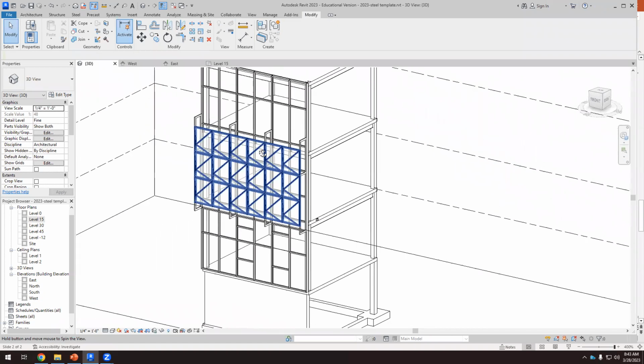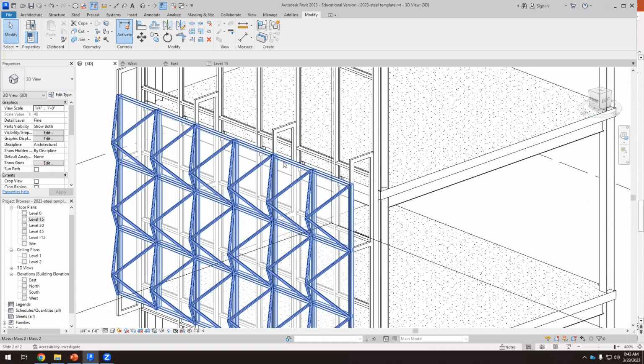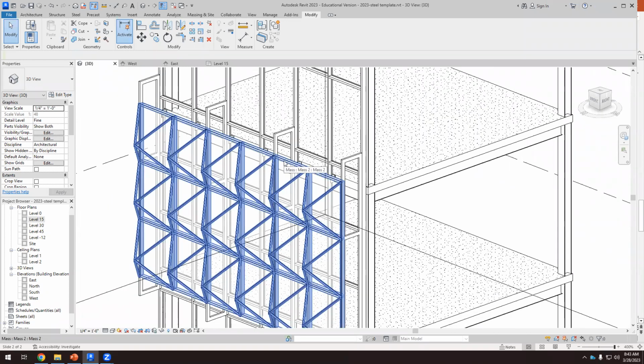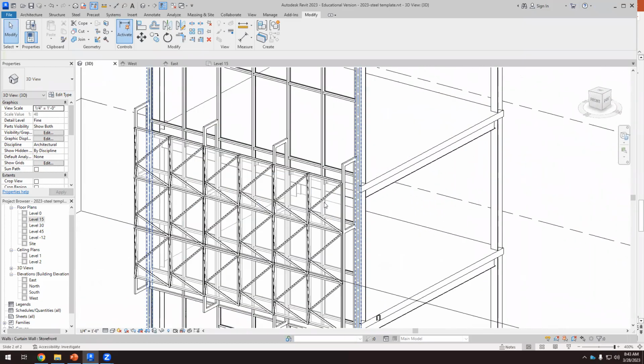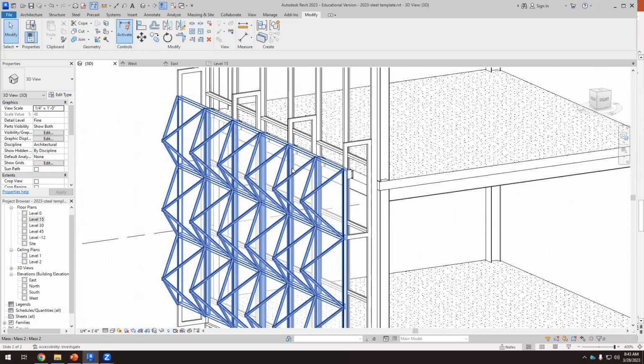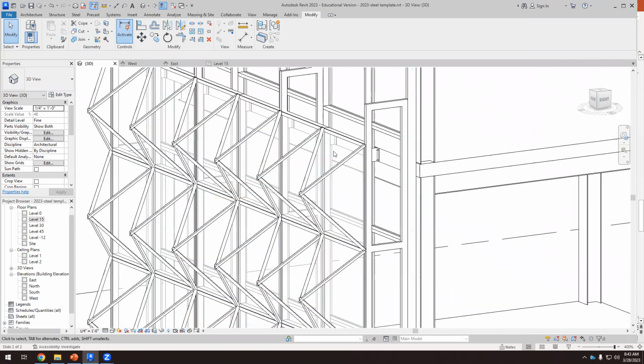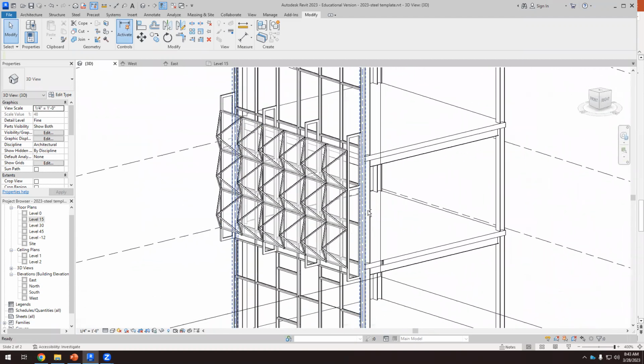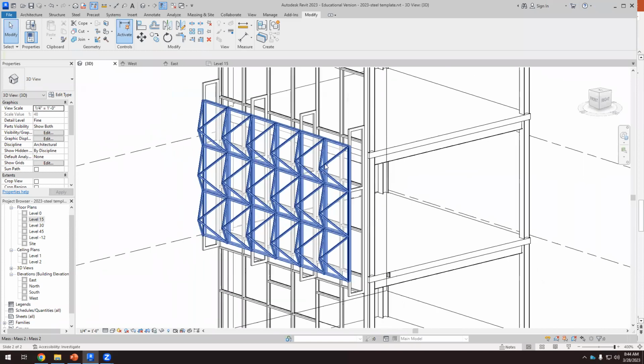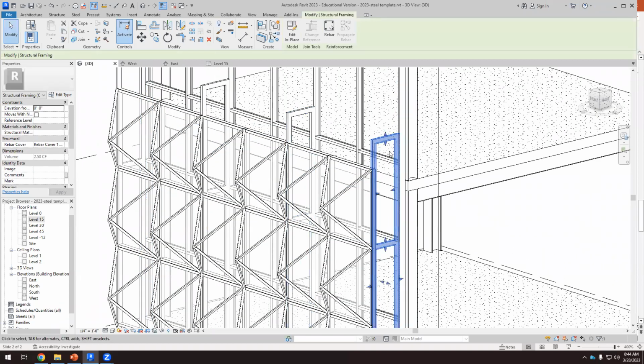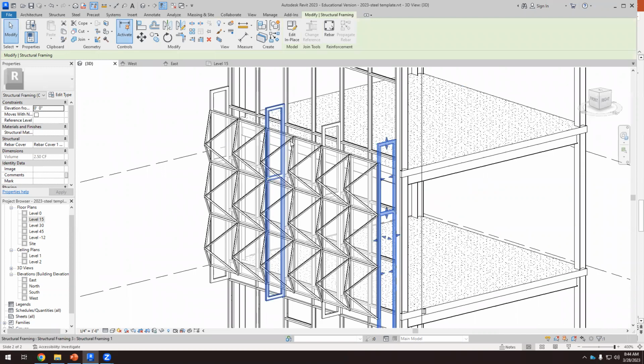Okay, so we have to rely on mechanical engineers because calculating double skins, especially for wind forces, because this is like a sail floating in the air. So if the wind is too high, the building could fly, kind of. Okay, but we have to keep in mind the wind force or the wind speed when we calculate these double skin facades. So this structure depends on the wind that we have. The more the wind, the more structures have to connect both layers. Okay.